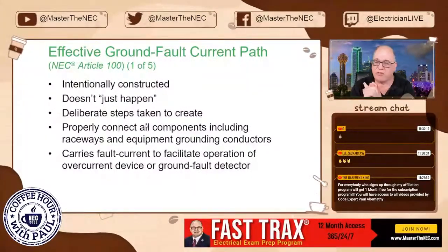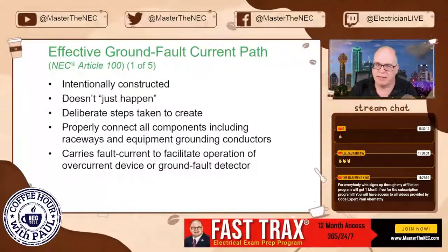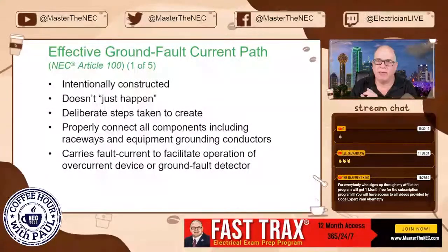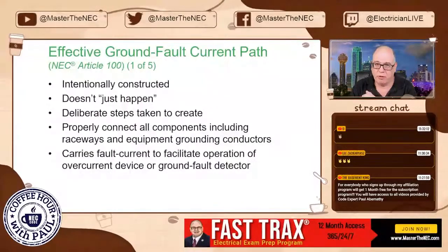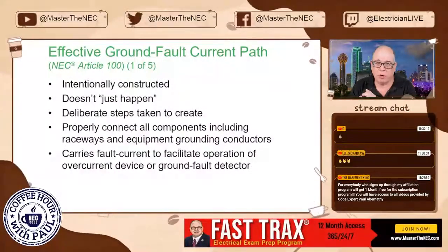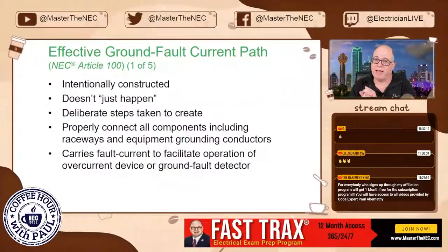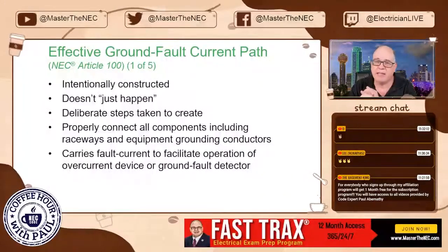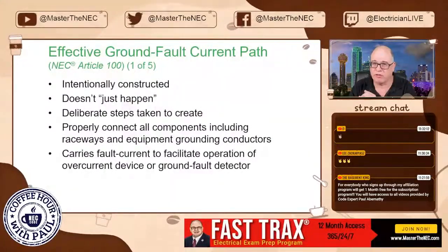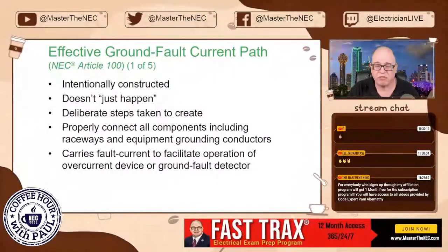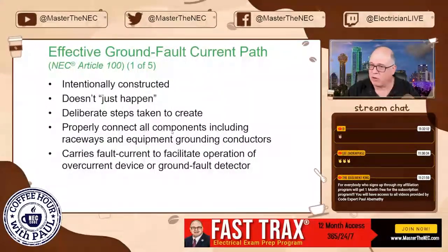That's why I'm challenging you out there now, all of you supervisors, all you leaders, all of you owners of companies. You need to hammer home the importance of this. I have been to many calls where fittings are loose, okay? I've been to many calls where people don't torque things properly, okay? When it comes to an effective ground fault current path, there's probably nothing more important than making sure we clear an overcurrent device when a short circuit, ground fault, or overload condition takes place. So let's make sure that that path is intentionally constructed. It doesn't just happen. We have to follow the steps to do it right.